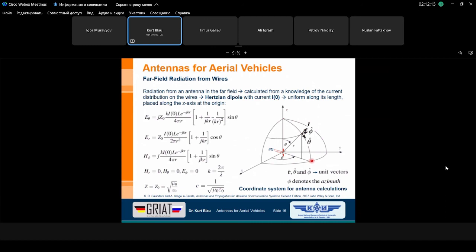In practice, if you have an antenna, not a Hertzian dipole, but an antenna, let's say a half wavelength or 1 wavelength dipole or whatever, or a monopole, then we can observe that we also have in this normally non-existent plane a very small value of the electromagnetic wave, I mean in the E field.